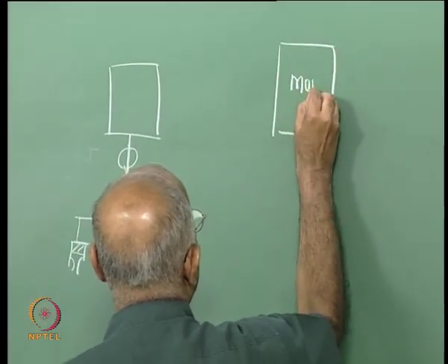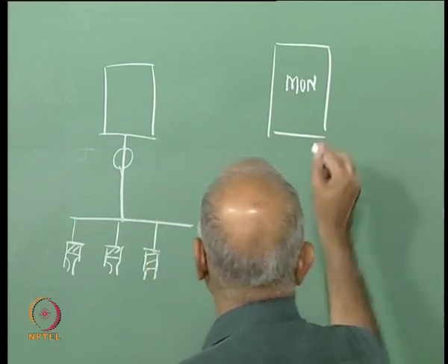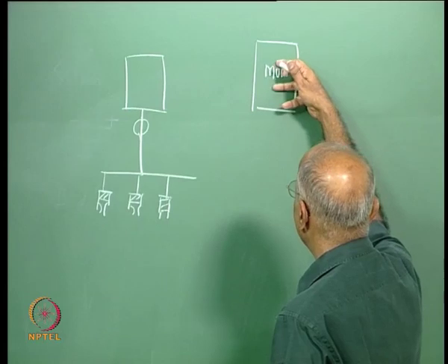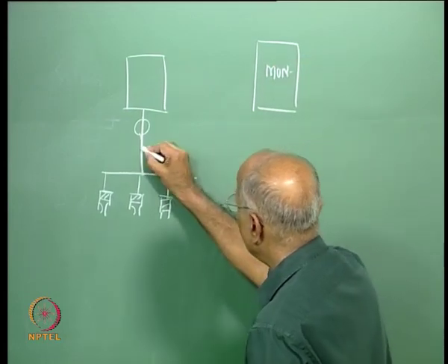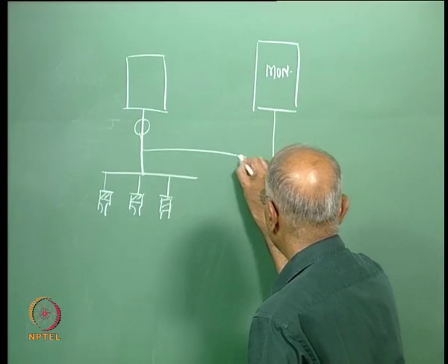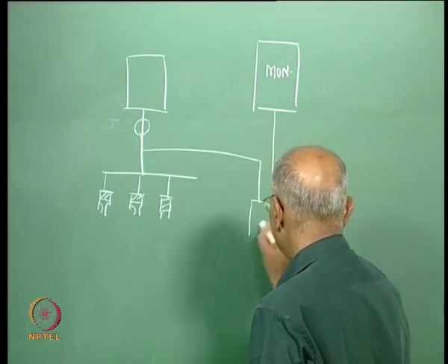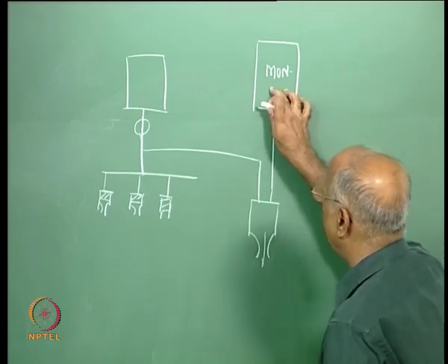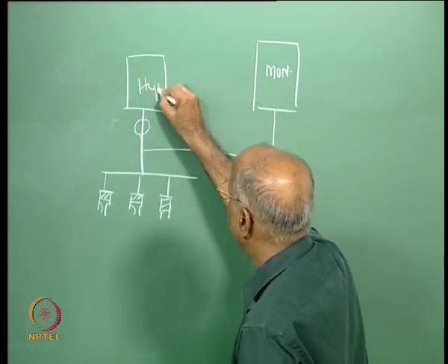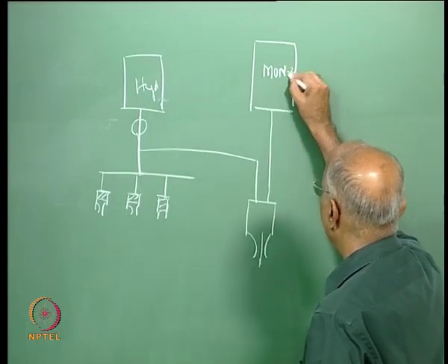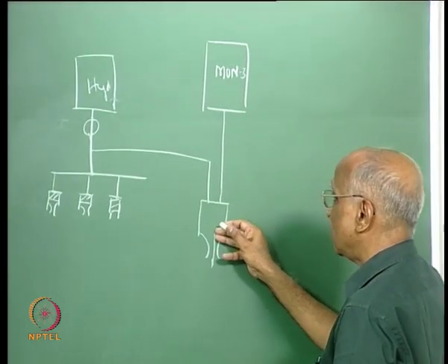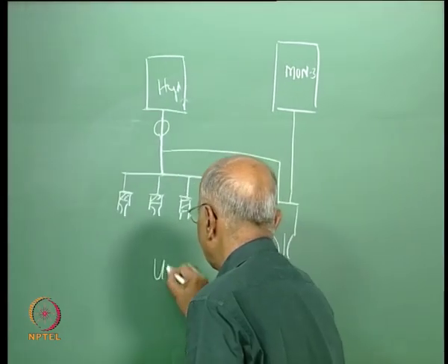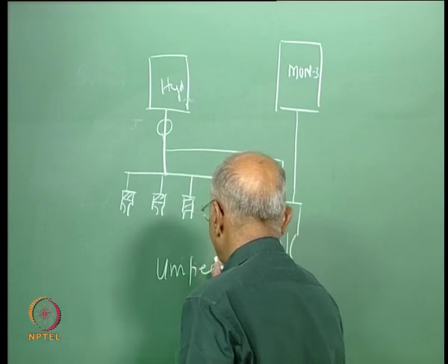You all will remember MON3 is something like N2O4 in which I add some amount of NO such that it has a lower freezing point, and I also take a little bit of this here. I also give this to a slightly bigger engine or rocket engine, and when I want to change the trajectory I operate it with hydrazine and MON3, or mixed oxides of nitrogen, to generate a thrust. When I want small corrections I use this, and this is known as a unified propulsion.